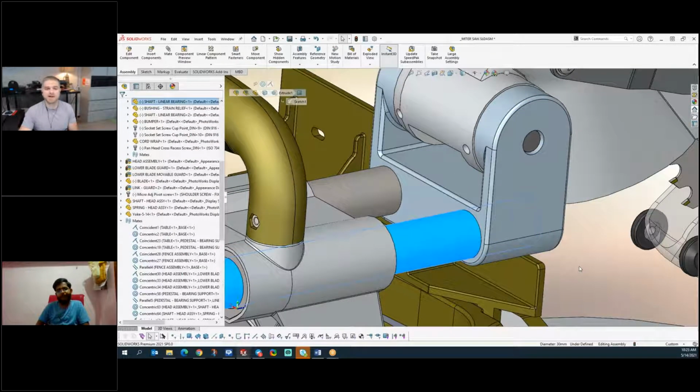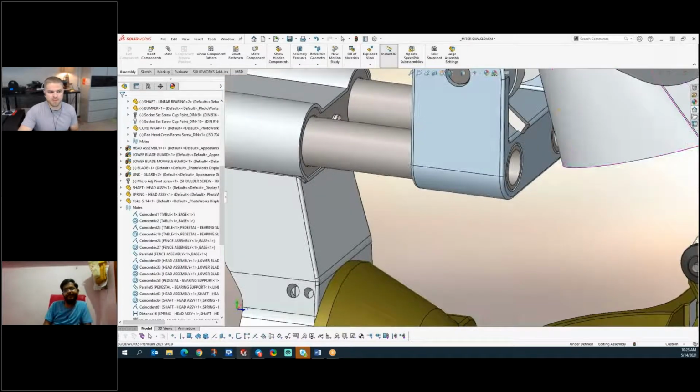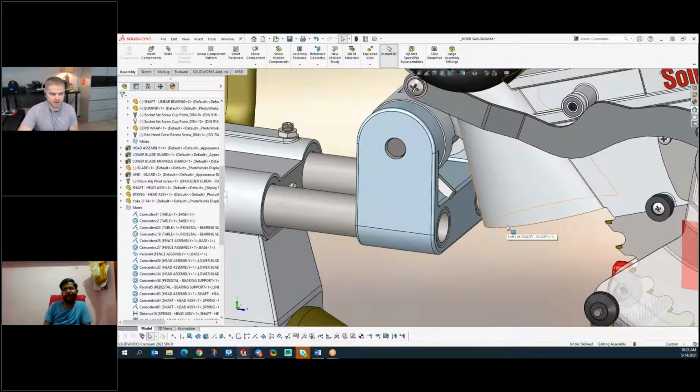And in fact, as you get more advanced and more capable in SolidWorks, that's what a lot of people tend to do. That's the difference between bottom-up modeling, creating the parts individually and putting them together, or top-down modeling, creating the assembly and populating the parts from the assembly down. Both of these approaches still get you a lot of advanced functions here in SolidWorks.